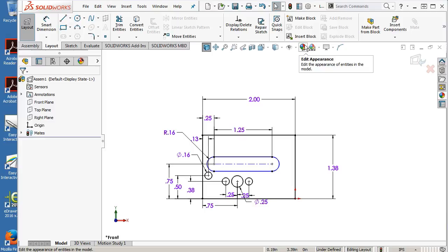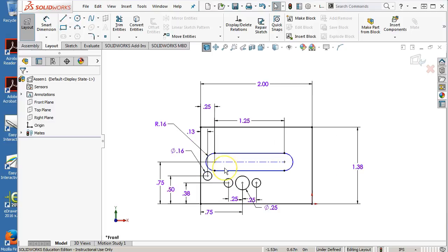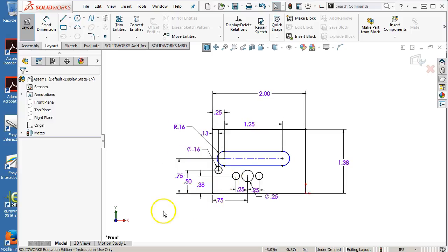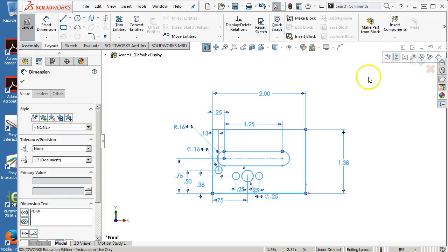So when I'm looking in this case for that cam motion and where this line actually needs to be, where that geometry should end up, I can relate the tangencies. I can relate some of the belt and chain and gear mates within the blocks, but not have to have separate sketches. All right, so kind of see where that lands us here.